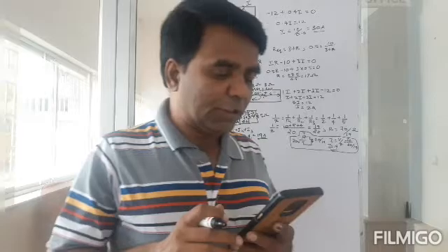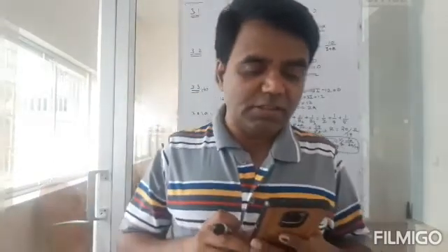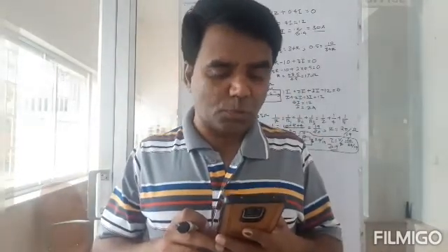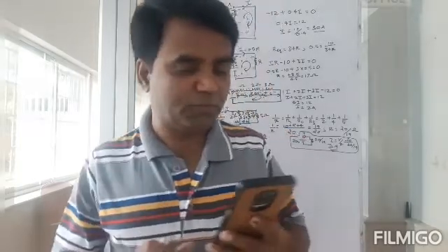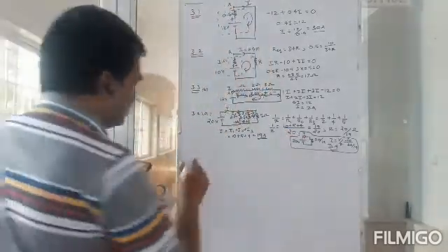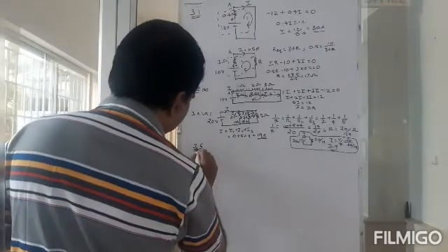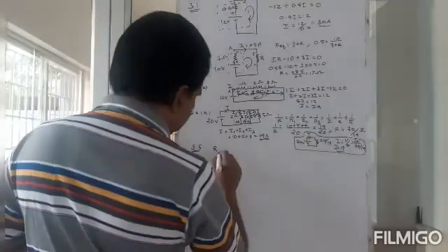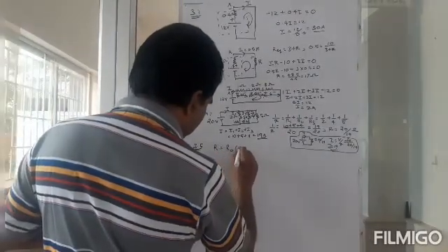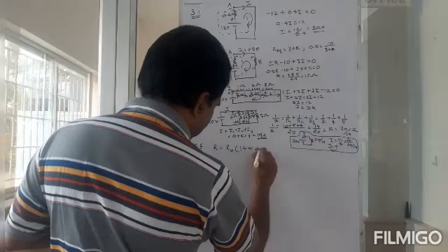3.5. At room temperature, which is 27 degrees Celsius, the resistance of a heating element is 100 ohms. Then what is the temperature of the element where resistance is found to be 117 ohms, given that the temperature coefficient of the material of the resistor is 1.7 into 10 to the power minus 4 per degree Celsius. So that is a straightforward application. But what do we know? For example, resistance at a different temperature is equal to R0 into 1 plus alpha into delta T.